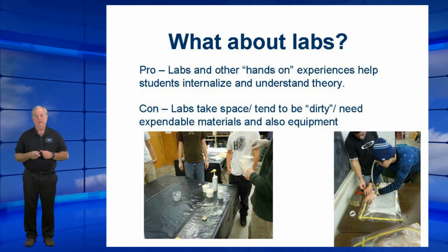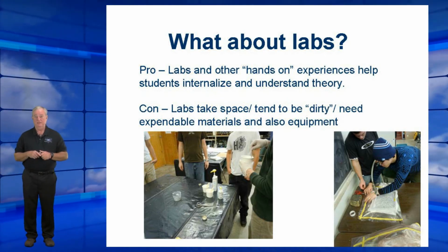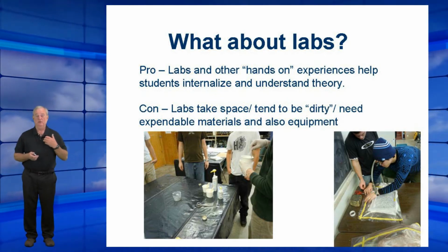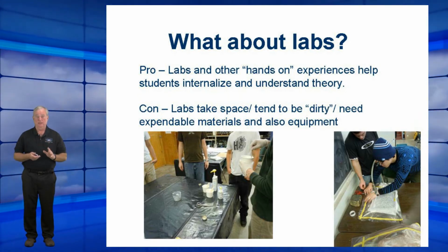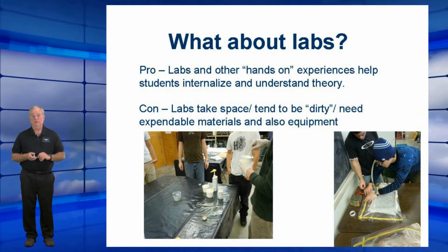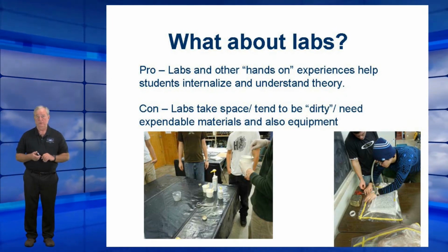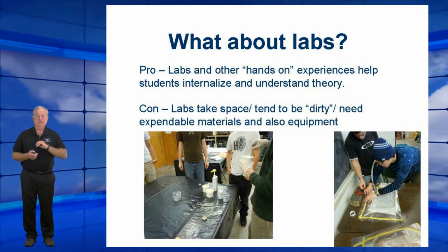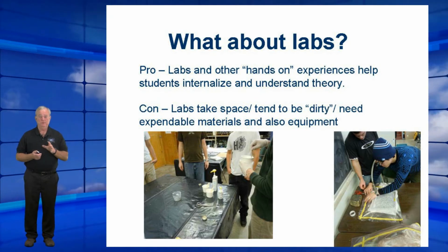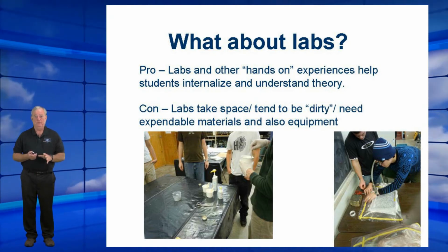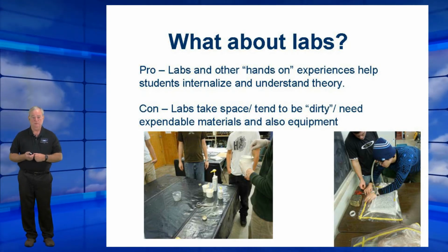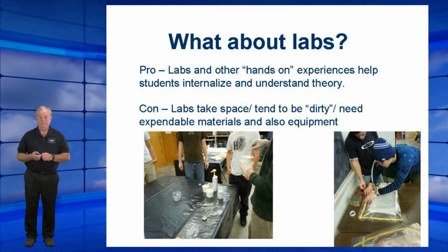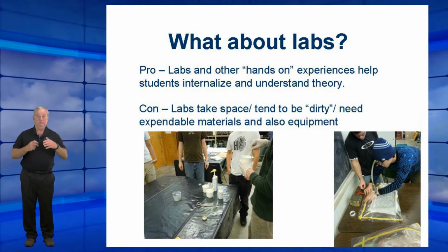The con is that composites labs tend to be dirty. Most people use a dedicated lab space for that because of the types of materials that are used. And the materials themselves are expensive and in many cases require refrigeration to store them, so they don't have a long shelf life.